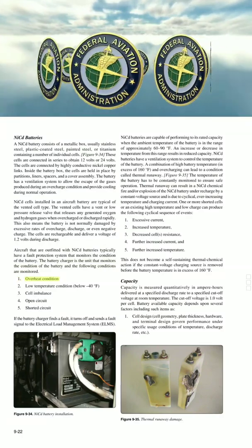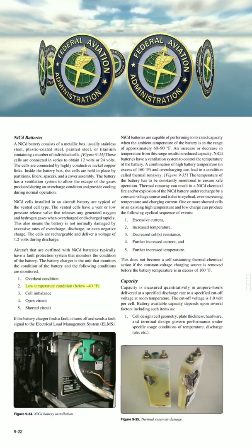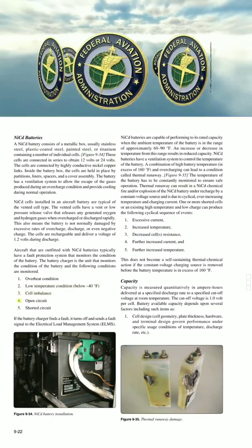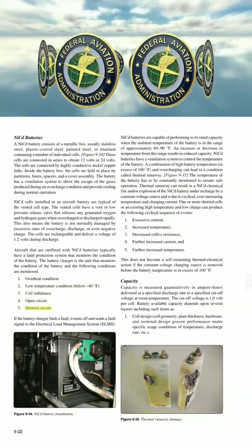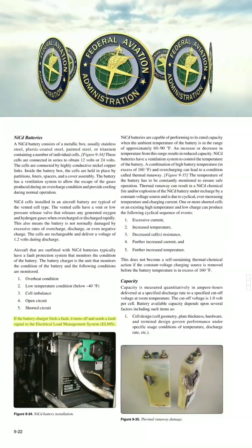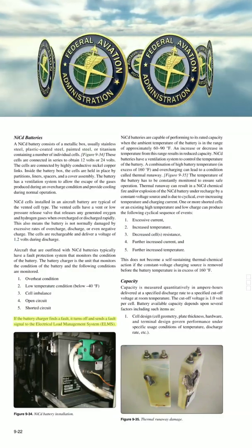1. Overheat condition. 2. Low temperature condition, below 40 degrees F. 3. Cell imbalance. 4. Open circuit. 5. Shorted circuit. If the battery charger finds a fault, it turns off and sends a fault signal to the electrical load management system, ELMS.